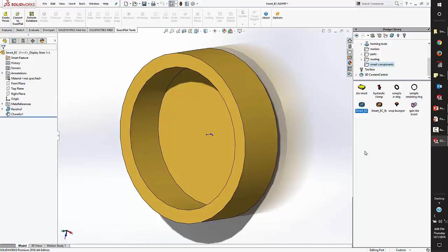All right. It takes a little bit of upfront thinking to make sure that you have all the cases covered, like, well, if I drag this O-ring to this size, it should be this size. You kind of got to have that in there. If you're ordering O-rings from a catalog, most of that information is all there for you. You can just reinstate it into that little dialog box I showed you. Fair enough? Kind of cool?